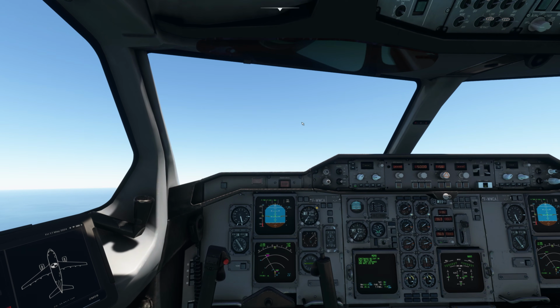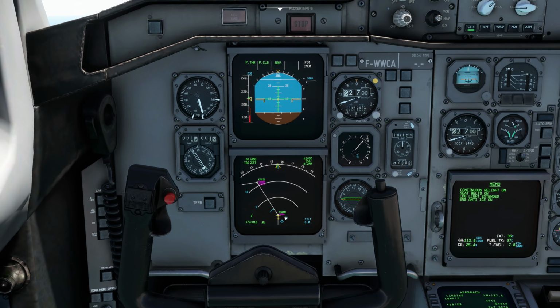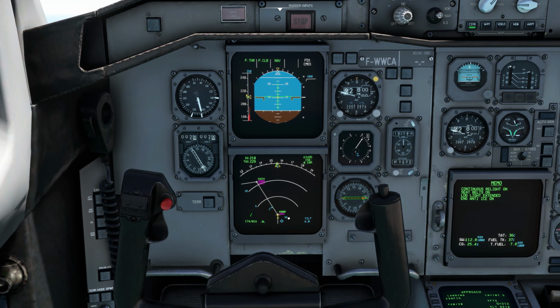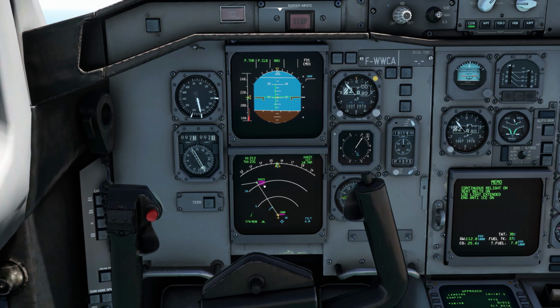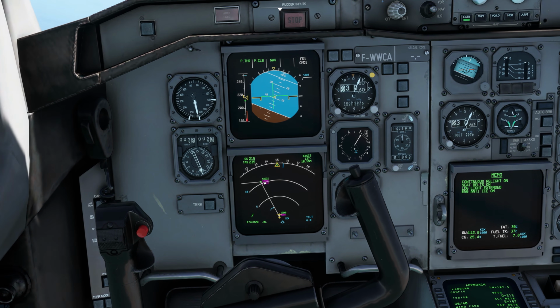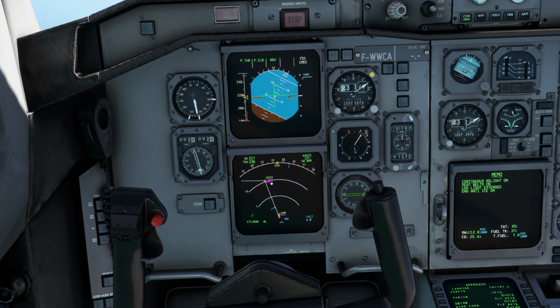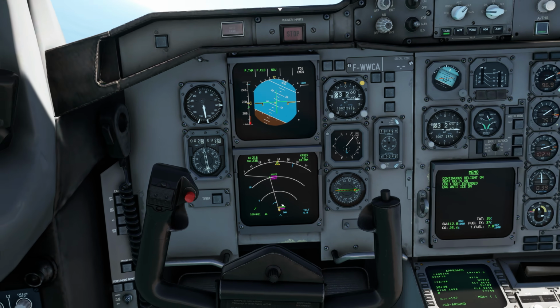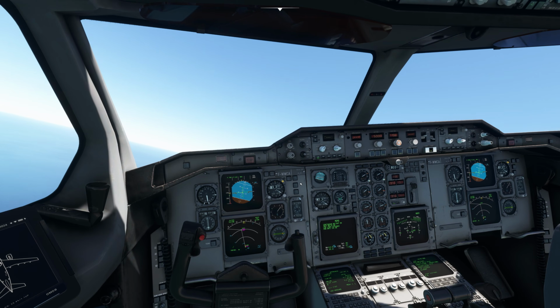Now, if I press this button, constraints, you will start seeing the constraints over here. 500 and above, this constraint is coming. Then over here, speed should not be more than 250 knots, and the plane should be at 5,000 or below, not above 5,000. So I'm using the profile mode.